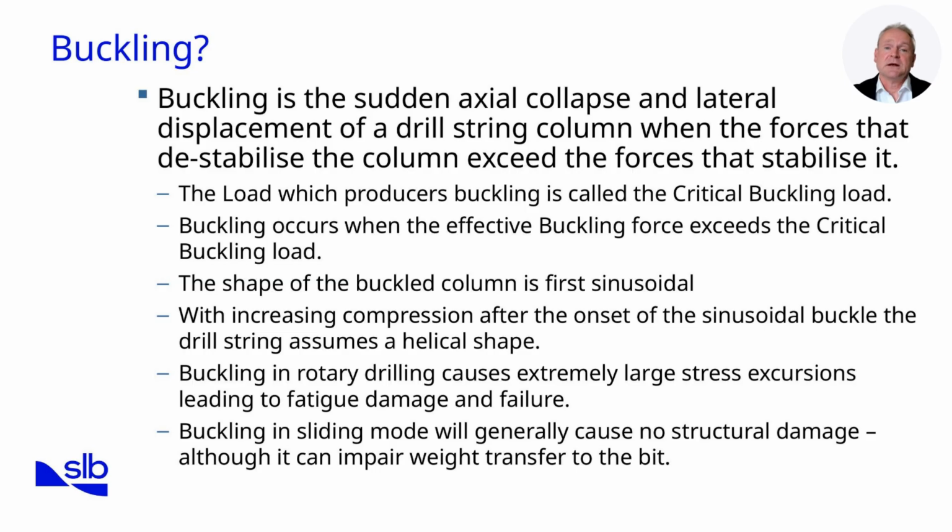Buckling in a drill string occurs when compressive forces acting along the pipe exceed its capacity to remain straight within the well bore. Unlike simple tension or torsion, buckling is a stability problem. Even a relatively small increase in axial load can lead to large lateral displacements once the critical load is reached. In practice, buckling starts when weight on bit and the weight of the collars impose axial compression on the drill string. If the applied force is greater than the critical buckling load, the pipe begins to deform.